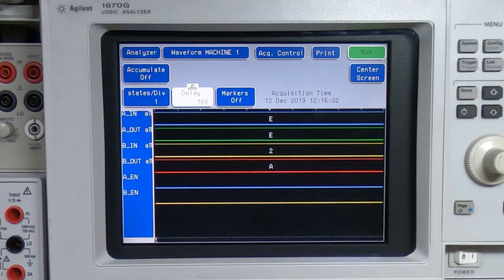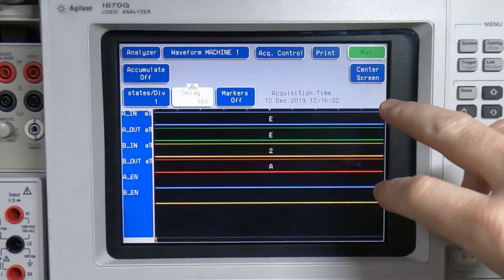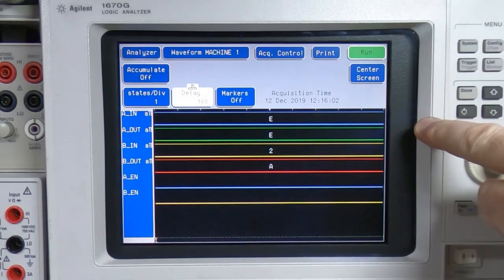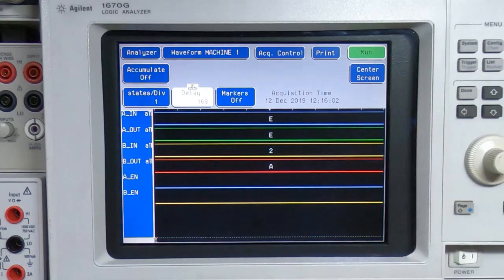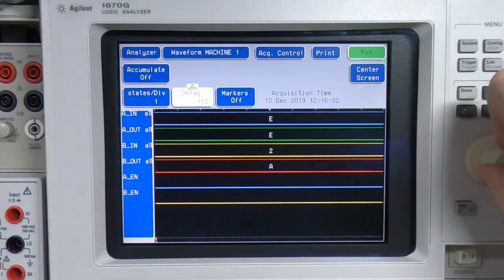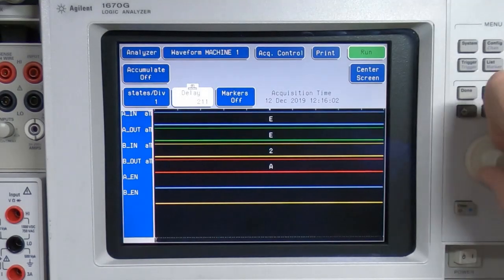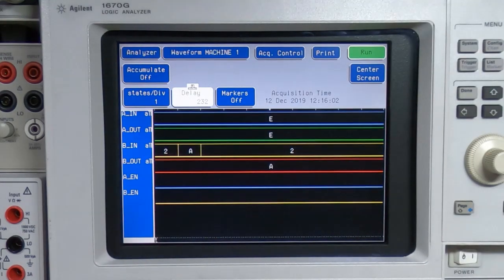Now in the next video what we'll look at is using the Fluke to explicitly manipulate these values so we can test all the possible permutations, because for buffer set A we're only testing a value of E, and it could be that there's a stuck bit there as well. This is where the logic comparator is much more useful, because it will continually scan as the machine's running, and the lights will flash if there's ever any mismatch.